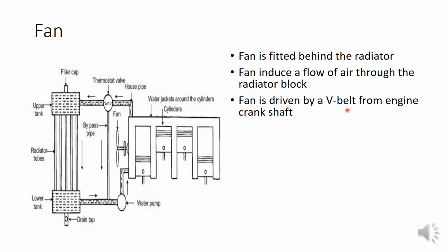And the fan is also driven by a belt from the engine crankshaft. So also it's like a pump. For driving a fan, we require some power. So it is again derived from the engine crankshaft through a V-belt. And sometimes this pump and fan will be on the same shaft. So the pump will be, instead of here, somewhere here, so that these two can be connected by the same shaft. So in some engines, the pump and fan will be on the same shaft.